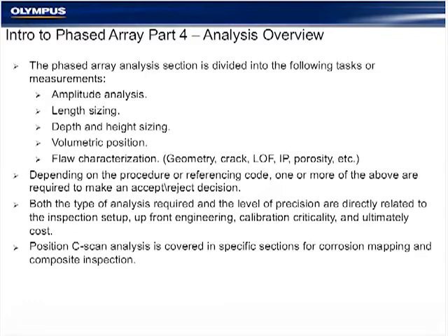Good coupling, good probe position, everything tight, all of the probe feet adjusted correctly so that we have a good gain sensitivity on both sides of the weld. All of those things are essential for good acquisition.